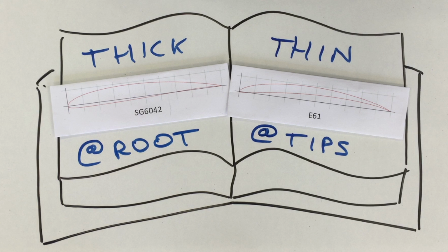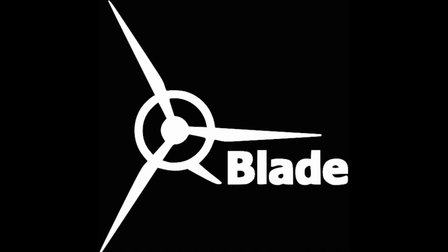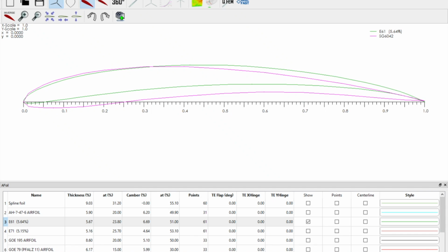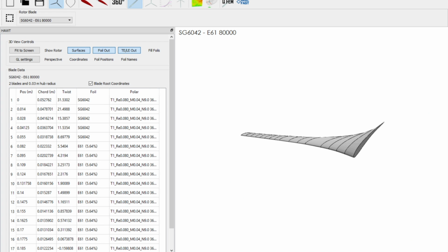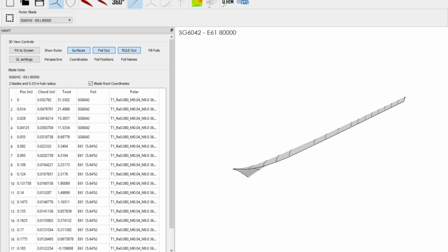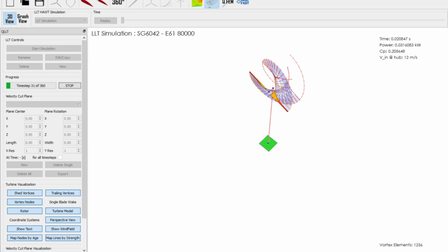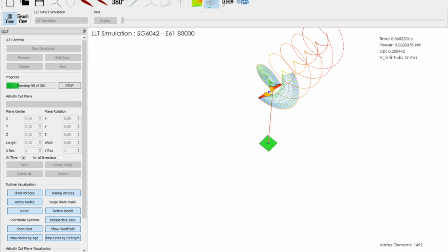To get an idea of how these aerofoils would perform during testing, we used the turbine simulation software QBlade. Whilst overly simplistic, QBlade essentially provided us with a proof of concept indicating that our turbine was likely to perform as expected. It also gave us an indication of the regions in which we could use our chosen aerofoil sections for good performance, as well as how much blade taper and twist we might use. However, more detailed calculations were still needed to determine these parameters exactly.